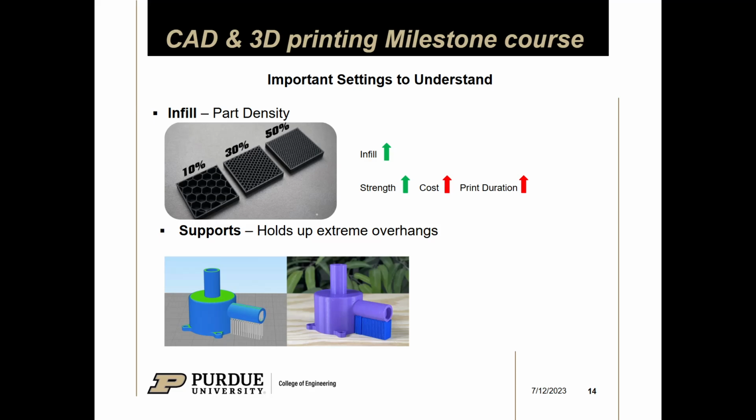But for me personally, I would increase the number of perimeters before the amount of infill I use, just because that typically yields a stronger part for the same amount of material. So yeah, does that make sense? Perimeters and infill, in my opinion, are probably the two most important settings. So if you don't understand, I'm happy to re-explain.